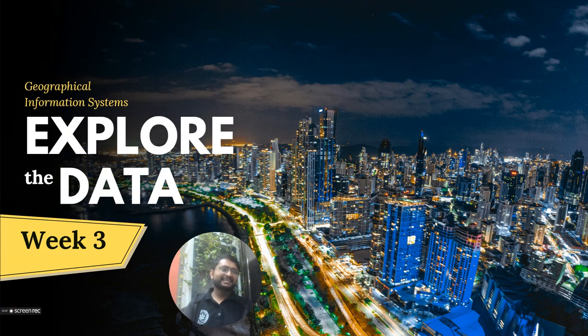Another thing is, you want to see how much urbanization happened in Bangalore, or let's say we take a classic example of the city of Dholavira. We have an old map of Dholavira from let's say 100 years back, and we want to see how much area is developed across that town. So we'll take that old map, scan it, make a digital copy of it, and put that into the QGIS system. In this way, we will get an image, and based on that, we will do the georeferencing.